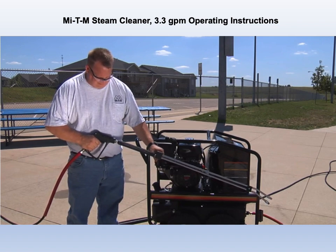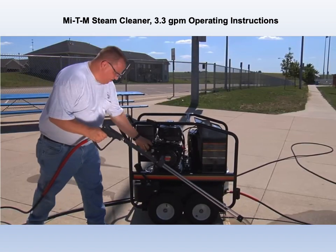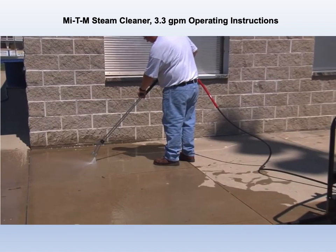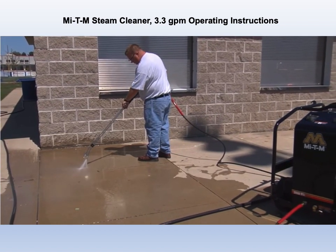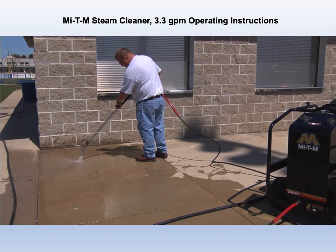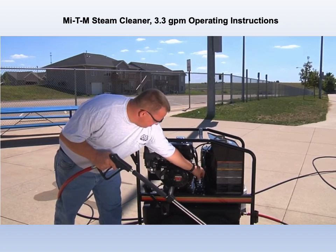Pull the recoil on the engine. The engine should start on the first or second pull. When the engine starts, release the trigger gun and close the choke. At this point, the unit is operating as a cold water pressure washer. It is important that you make sure the pressure washer never runs in the bypass mode for more than 2 minutes. To operate as a hot water pressure washer, move the burner switch to the on position.